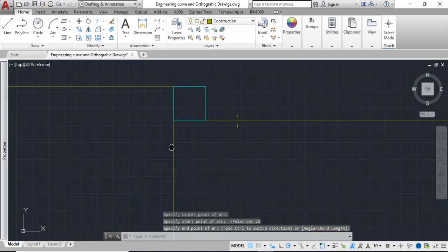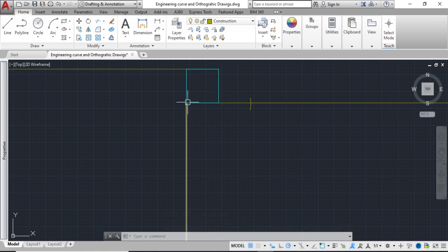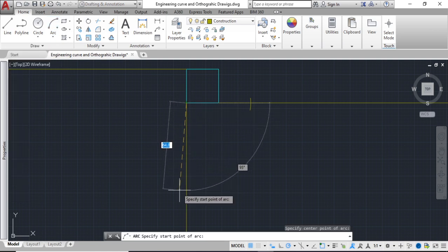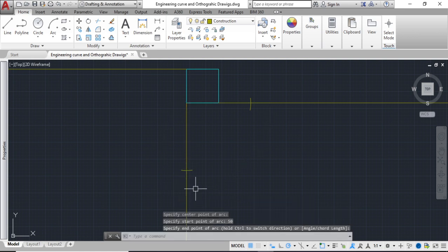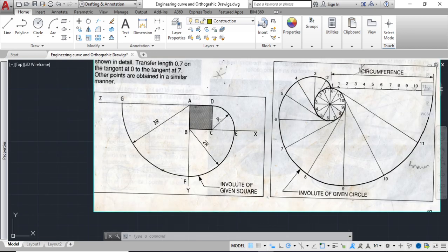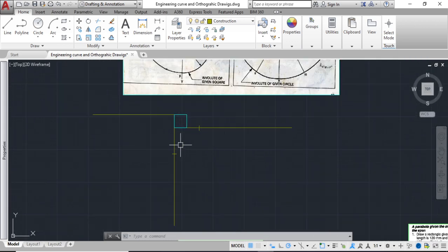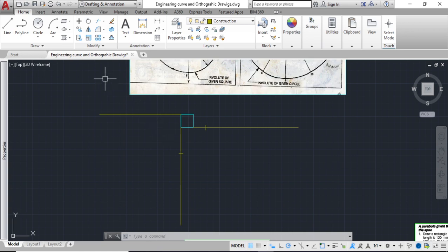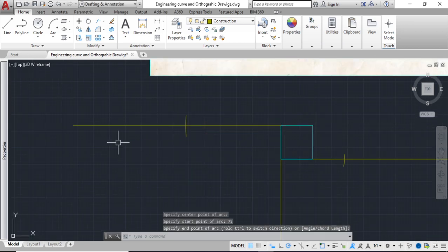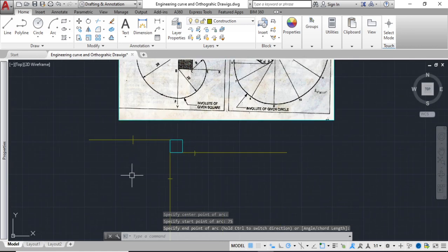Good. So this one is 50 now, because this side plus this side unwound gives you 50. So center, start, end again. 50. Enter. Boom. And then 75 on this side, because you're unwinding the circumference: R, 2R, 3R. So if R is 25, it's 25 and 25, 50, plus 25 is 75. Sorry, I kept saying 150, but 3R is 75. Thank you for the correction. Center, start, end. This should be 75. Enter. Cut the line.